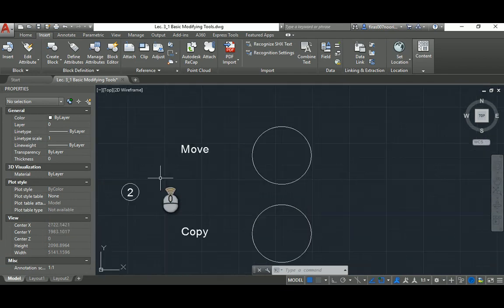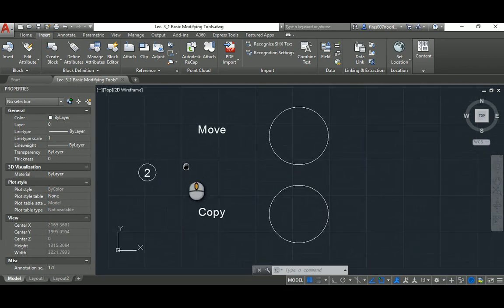Now, the most common and most frequently used commands are move and copy. From now on, we're going to talk about twin commands, and move and copy are very similar. As the names easily explain, move is just going to move the object from the old place to the new place, and copy is doing the same thing, just making a copy of that. Very similar to copy and paste and cut and paste in Windows, and both of them need almost the same sequence of steps.